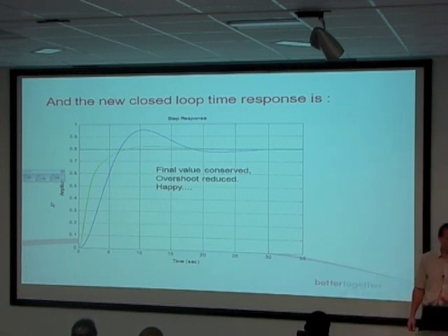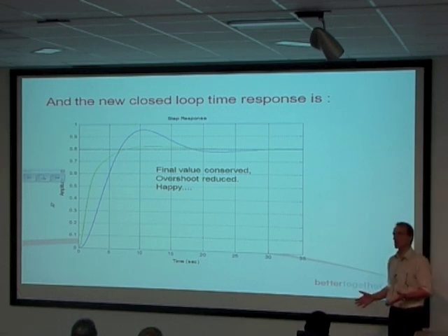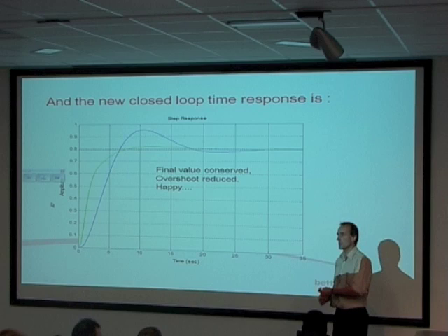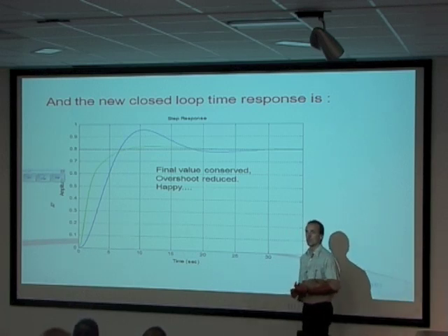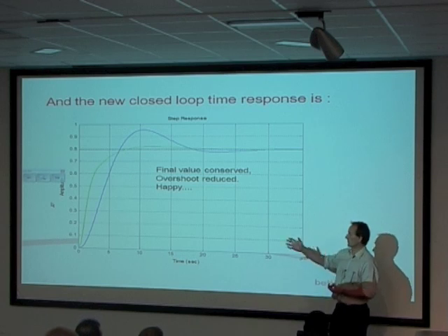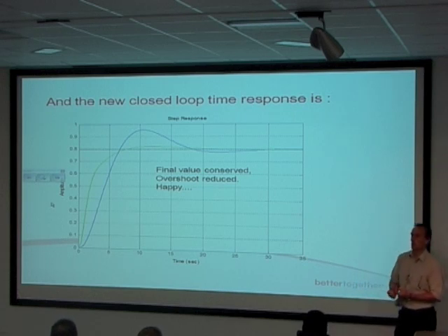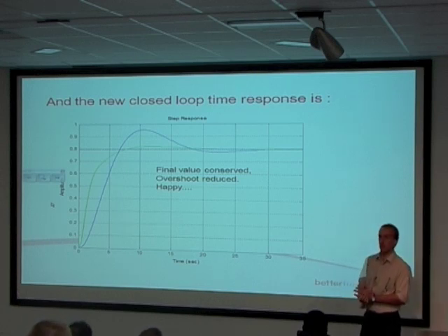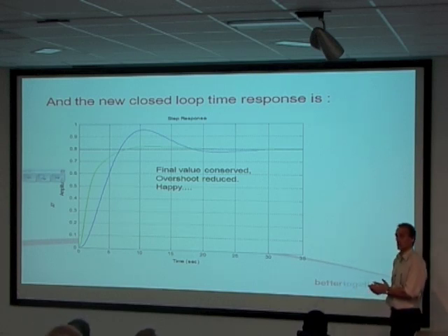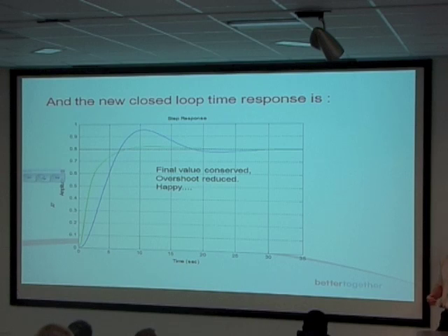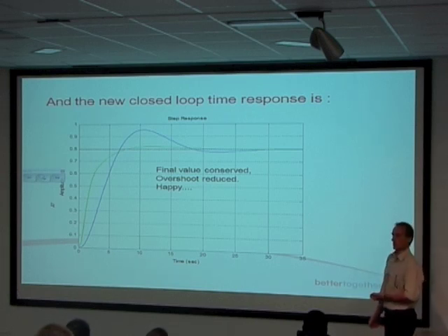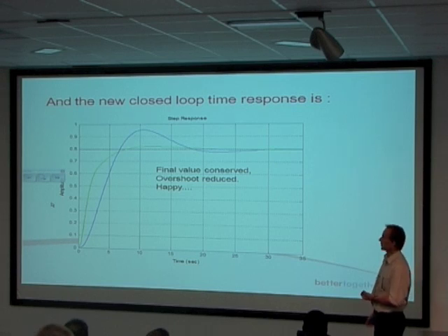Implementing the compensator, well, there are a number of ways of doing that. Again, it depends on what it is you're controlling. You can implement a lead compensator very easily in software. If this device has got a software loop somewhere in there between our demand, you can implement a lead compensator in software. You can implement a lead compensator just as a simple piece of analog electronics, or indeed digital electronics if you want to go that way. There's all sorts of ways of doing it. But this is one of the first examples of an off-the-shelf controller, and we can do all sorts with it.